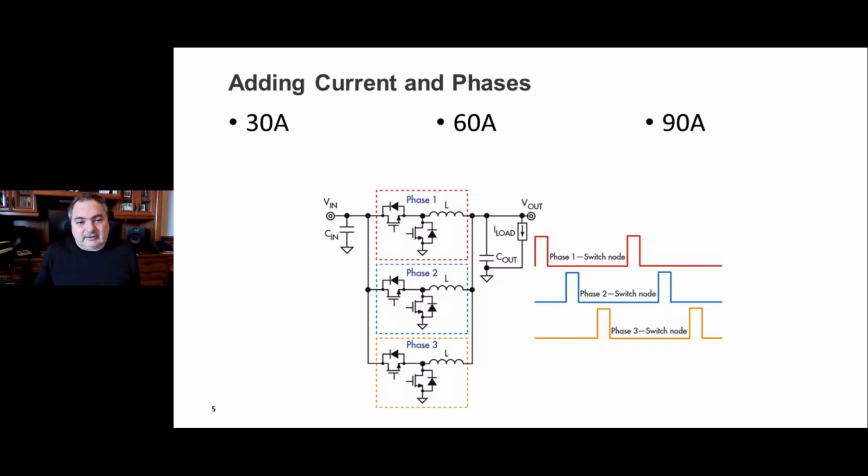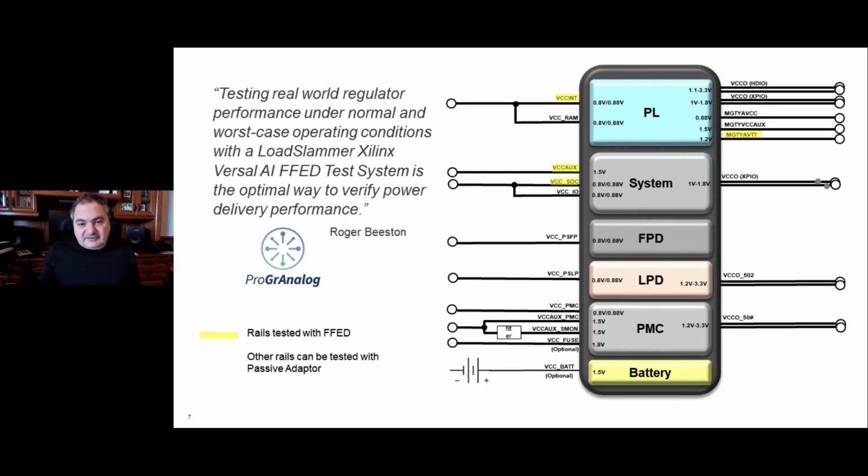So there's lots to think about here, especially with non-linearities in these multi-phase solutions, as every vendor who makes a power management solution has their own proprietary architecture. And these architectures are very sophisticated. They have a lot of firmware, hysteresis, non-linearities, and time constants. In the really sophisticated ones, they even have mini processors in there running the firmware and the opcode. So there's a lot of potential for non-linearities to creep into the solution, and we need to test these non-linearities.